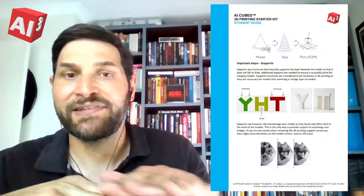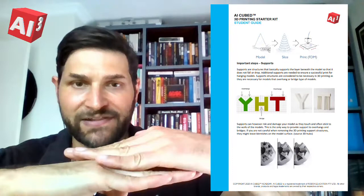The last thing I'll talk about today in our guide, and again I'm going to let you read most of it yourself, is the finishing process, and in particular what we call adding supports. Supports are really important to make sure our prints don't fail. There are a few basics about printing supports and 3D model files. Number one is you always want to print it on a flat plane, so the flattest surface of the object is on a flat surface.